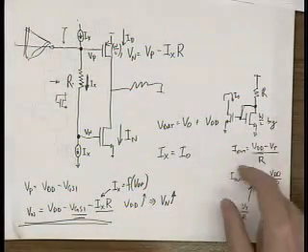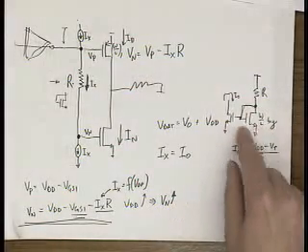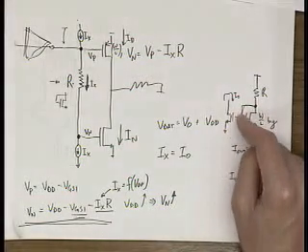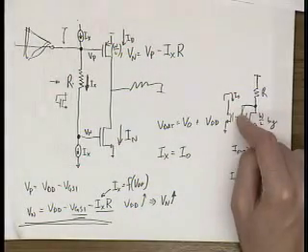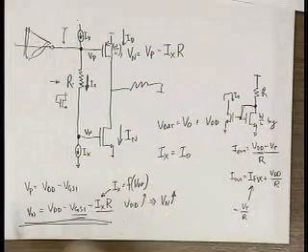So this doesn't work exactly because, remember, there is some VDSAT on this device that is current dependent. But if you make this device big enough, you can kind of get rid of that, and the residual stuff might not be so bad. Okay? So that's one thing.